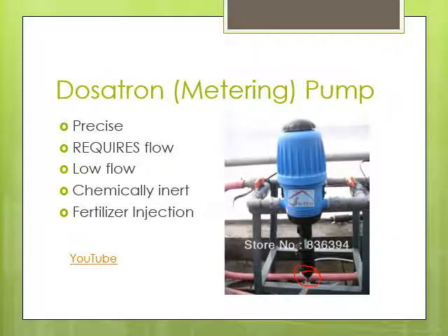There is wear and tear on the inside of this cylinder from it going up and down, especially if you don't have proper filtration on the inlet side, because sand gets in. And when sand gets in, it starts to scratch the sides. And then when the piston's going up and down, water is able to leak by and it doesn't work nearly as well. So filtration before water goes into these is really important. And I have made a mess of that picture.